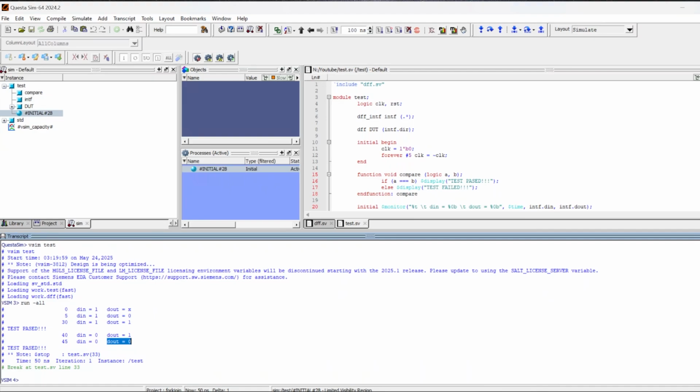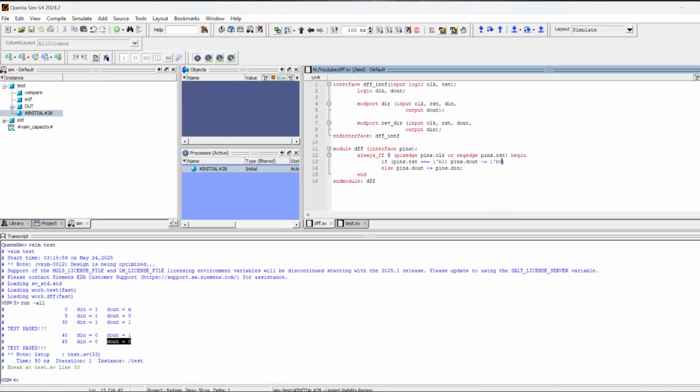So coming back to our interface, this was the generic way of declaring the interface inside the port of the design. There are other means. For example, instead of doing this, you could have directly mentioned the type of the pins to be the name of the interface itself instead of using the interface keyword.